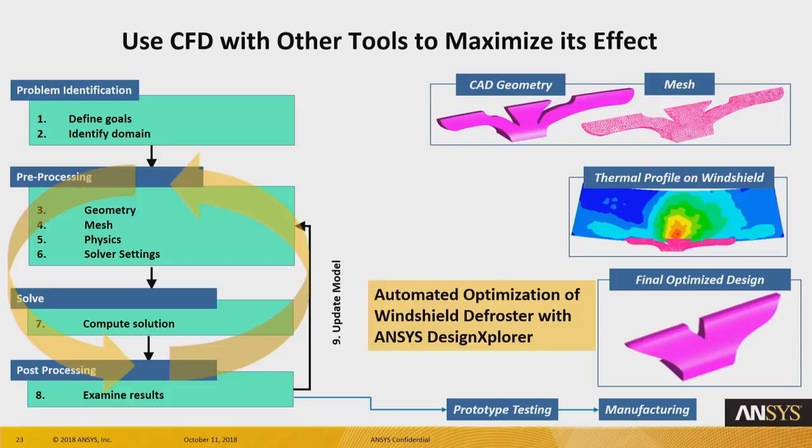In this particular example, we are using the conjugate heat transfer analysis with mass transfer in order to solve the problem of defrosting. As you use the vehicle in the winter conditions, there's a thin layer of ice that forms on the windshield. The task of the CFD analysis in this particular case is to solve for the fluid flow of hot air from the defroster on the car, and then calculate how quickly this layer of ice is going to melt under the given temperature field.